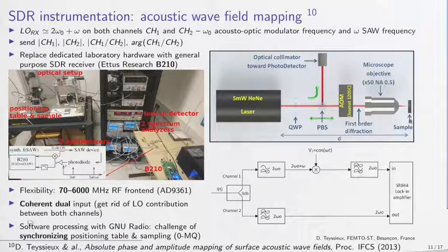So we have a device under test. This device under test is a radio frequency bulk acoustic or surface acoustic wave transducer. Bulk acoustic as a resonator like your 8 megahertz quartz oscillator, or radio frequency surface acoustic wave devices for radio frequency filters as you will find in your mobile phone. And we wish to know not only the electrical characteristics, but because these are based on piezoelectric substrates, we wish to know the vibration amplitude of the mechanical wave, the acoustic wave propagating on these piezoelectric substrates.